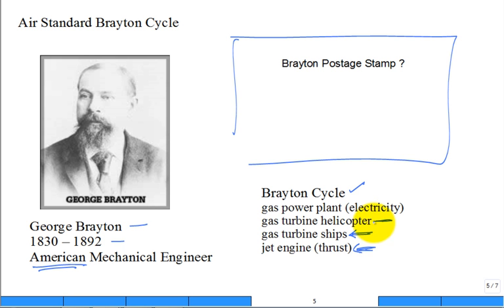Also, helicopters, as I mentioned, that's the drive. So if you've been in the military, you know that. How about tanks, the Abrams M1? That's all a gas turbine engine. It's not reciprocating pistons. They used to be piston-cylinder reciprocating diesel engines, but they've been replaced. Why? Lower weight for higher power output. So the package can produce a lot of power for a little bit of weight.